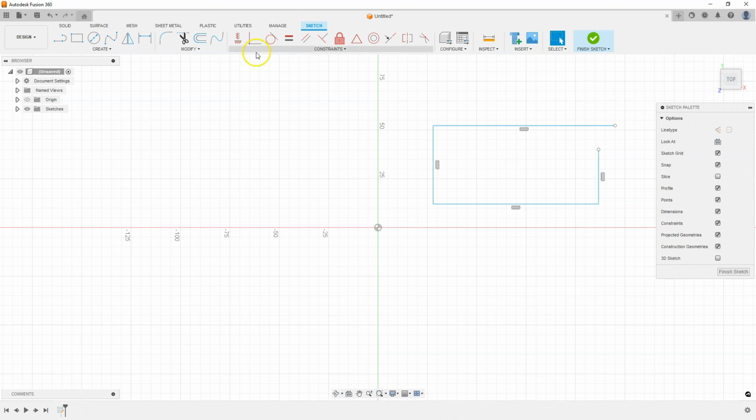Let's select coincident constraint and select two endpoints of two lines. And now these points are connected to each other. Press the escape key to cancel this command, and we are back to the geometry that was at the beginning. We will continue this example in the next lesson.